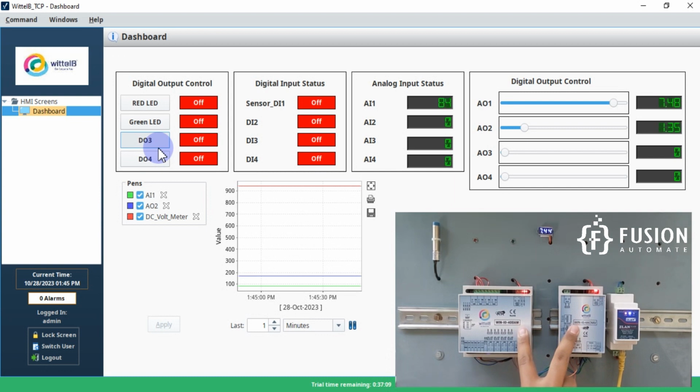This Modbus IO card is based on Modbus serial communication. That is why I have to add this Modbus serial to TCP converter gateway to convert Modbus serial data into Modbus TCP data, and then connect to Ignition SCADA, if my requirement is for Modbus TCP.